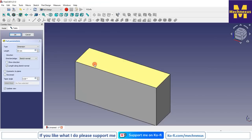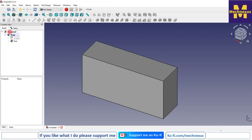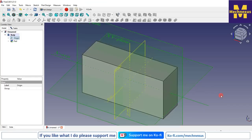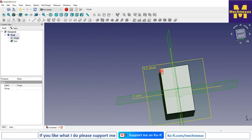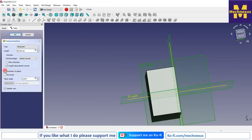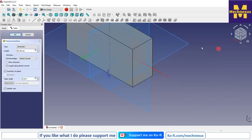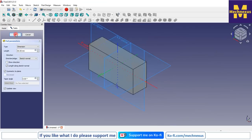So you can see that it is extruding in one direction only. I can make it symmetric, so click on symmetric to plane, and now go to the model and hide the origin plane. So you will see that now our extrusion is symmetric, and if I uncheck it, then my extrusion will be in one direction. And now I will say OK.